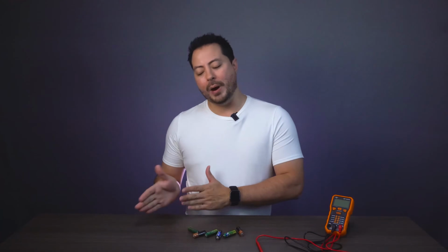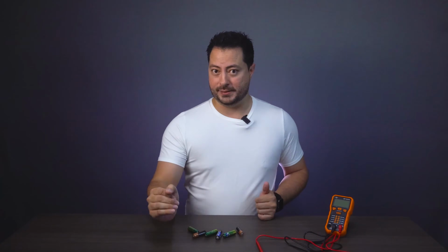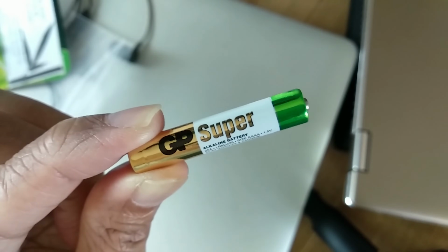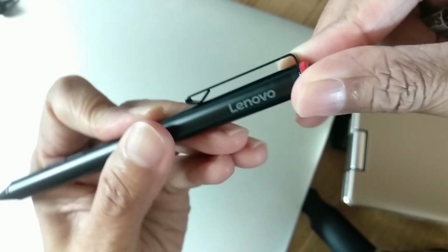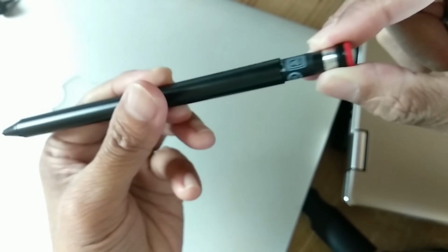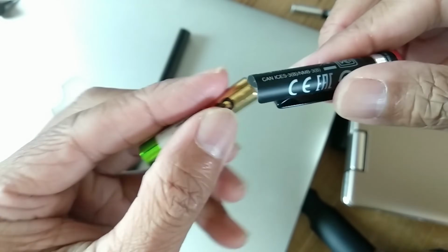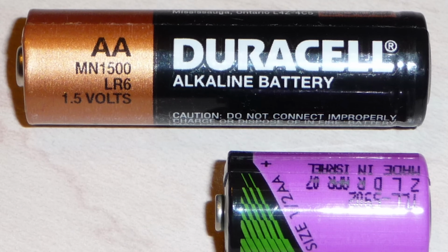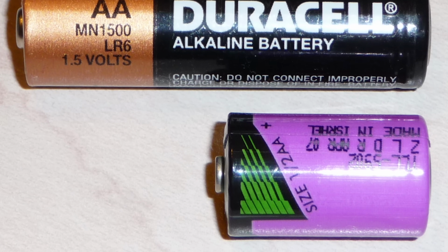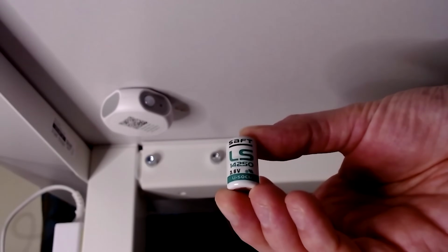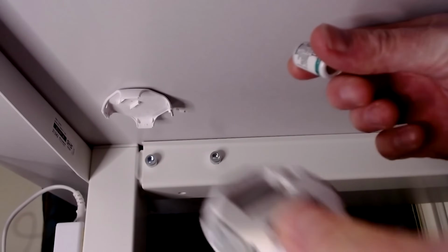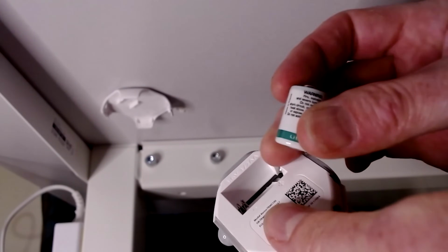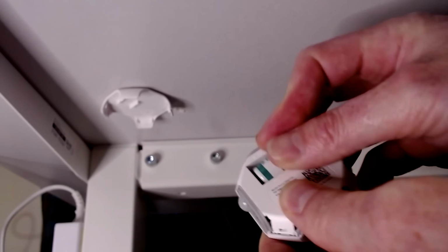We also have AAAA-type batteries with 4 A's, which are very thin, about 8.3 mm in diameter and 42.5 mm in length. And you can find them in some tablet pens, some laser pointers, very slim remote controls, and some medical equipment. We also have the half AA type battery, which, guess what, is half the size of an AA battery. But instead of providing 1.5 volts, it provides 3.6 volts. And it has more specific uses, and usually these batteries end up being soldered onto circuit boards like security systems and PLCs.